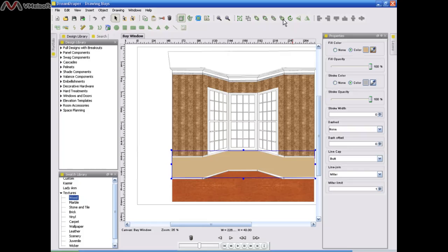I click, and in our last lesson on the order command we said sometimes you have to click multiple times to move that object into the exact position that you want. And you notice each time I click, you're going to see something. Now, my wall lines, those lines that I drew, the vertical lines, are still behind that polygon shape. So I'm going to continue to click until the lines are on top. And again, I'm clicking on this move down icon at the top of my toolbar. There!